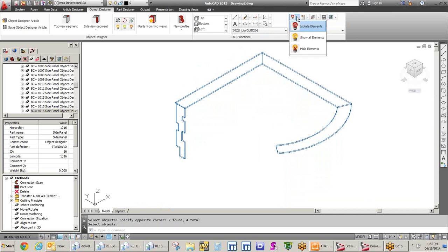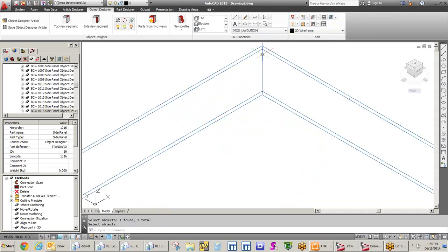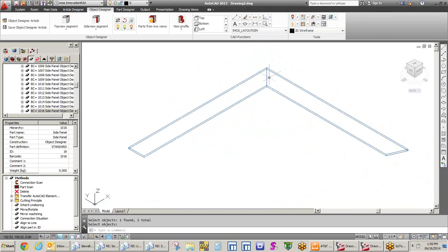We'll tell this that we want to get it down to just these two parts that we're working with. You'll notice in this particular example that these parts were actually mitered right at the corner, and unfortunately that's just not an appropriate location in most cases to be able to break a die wall, and understanding that, I'm able to control each and every part within this.